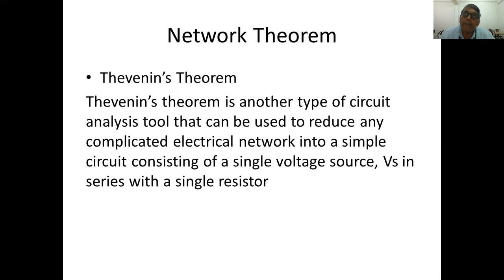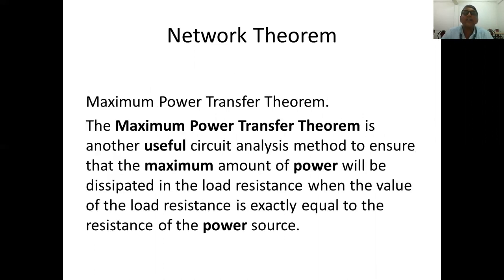Thevenin's theorem is a theorem which we apply to a complex circuit. In this, that complex circuit is converted into a simpler circuit having Thevenin's voltage and Thevenin's resistor in series with that. The entire complex circuit is converted into one voltage source and one resistor. That is what you are going to study.